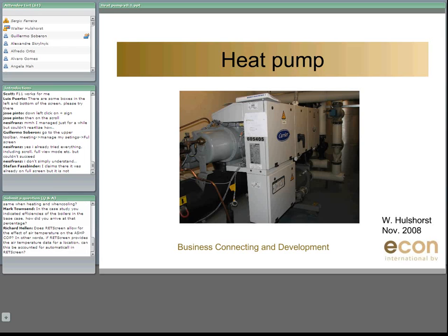Well, yes, you can do this if you know the fuel consumption of your boiler, and if you have an estimation of the efficiency of your boiler and the area of your house, you can make a very rough approximation of the heating needs for your house. But you can always go into more detail, and an expert will make a very detailed analysis and give you a very concrete heat load in watts per square meter for your house, and this will probably help you to better dimension your heating system.